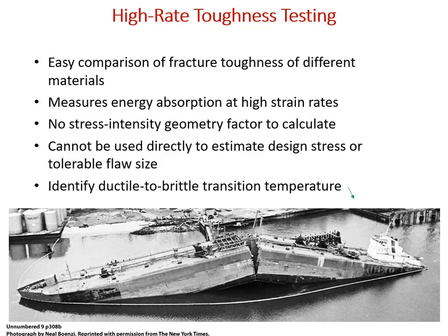There's no stress intensity geometry factor to calculate. These are standard test sample geometries, and so we don't have a Y factor. And we can't use it, unfortunately, to directly estimate design stress or tolerable flaw size. So that's the downside. We can't use it as design input. But if we have a material that we know works in the design, that we know perhaps even conforms to a given safety factor, then we can use this test for comparison for other materials that might be just as good or better. And certainly we can preclude materials that wouldn't work.